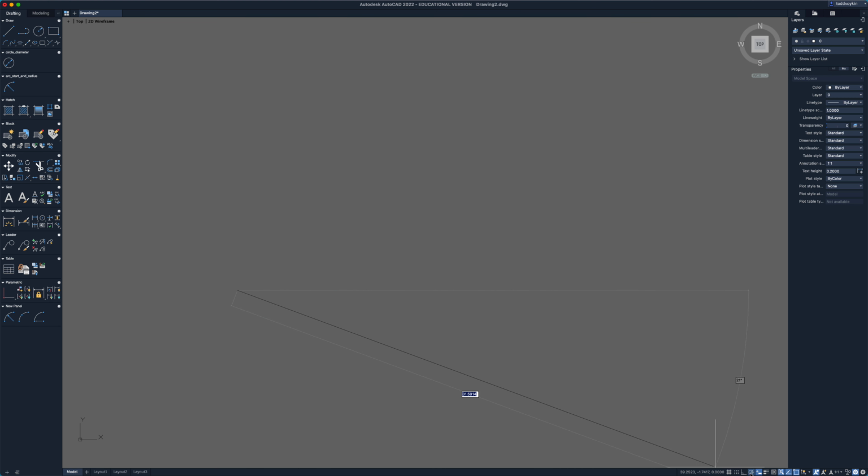So when we come down here again, I can click on that, or I can use the shortcut, which is Command U. So if I go Command U, it is now turned on, and as I come up here to the 0, it's going to snap there and give me that little green line. Okay, now it depends what it's set to and where these green lines will appear. Now as I move further up, you can see I'm at 7, 8, 9, 10, 11, 12, 13, 14, 15. It's snapped in at 15. So every 15 degrees, there's 30, there's 45, there's 60, there's 75 and 90, and so on and on.